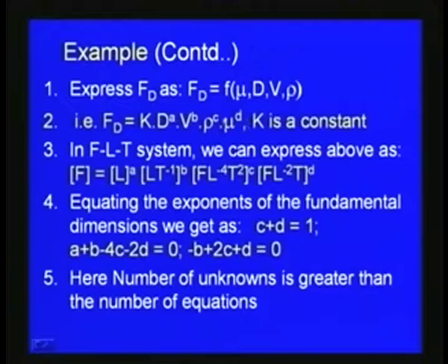Now, as I mentioned, we will be using either mass length time units or force length time units for the dimensional analysis. Either one of these can be used. Here we are dealing with the drag force, so let us try to solve this problem by using the FLT system, or force length time system. The drag force, in terms of the unit, is force, so we can just represent it as F.